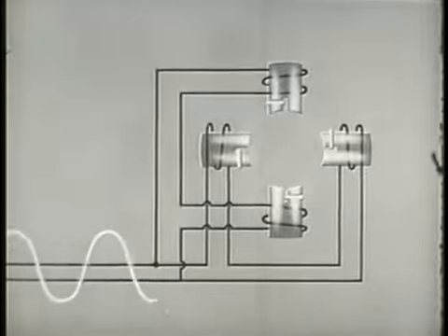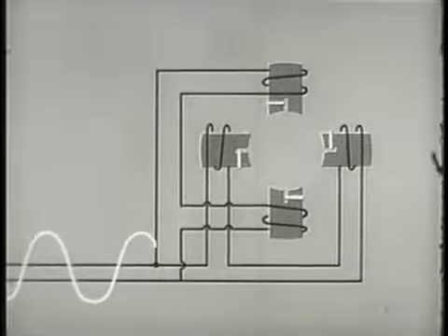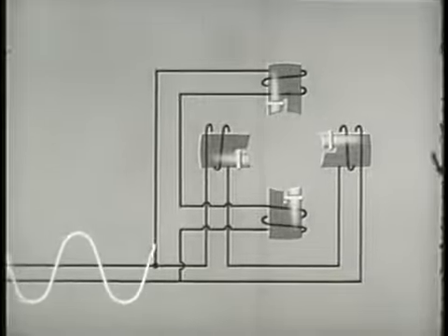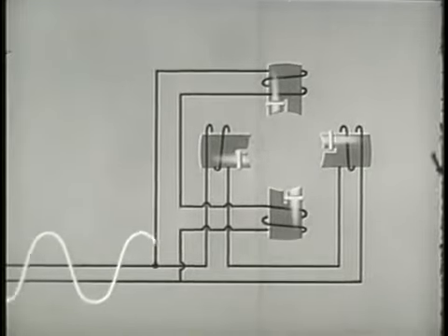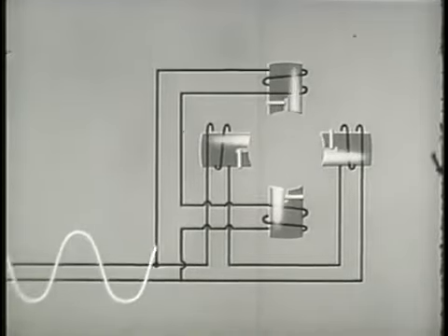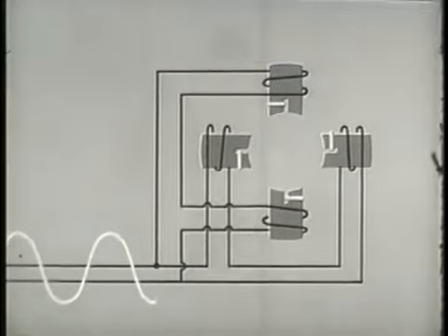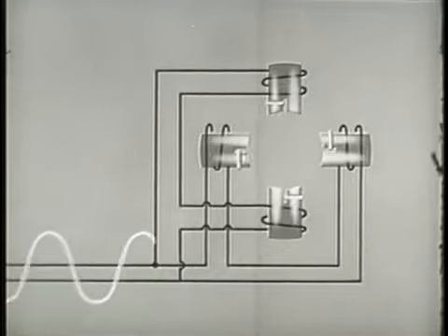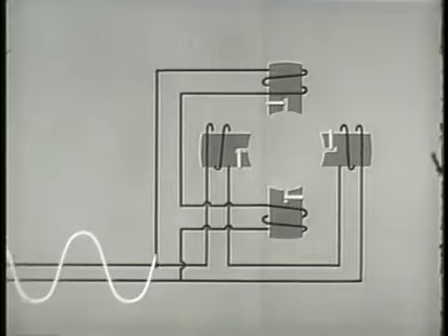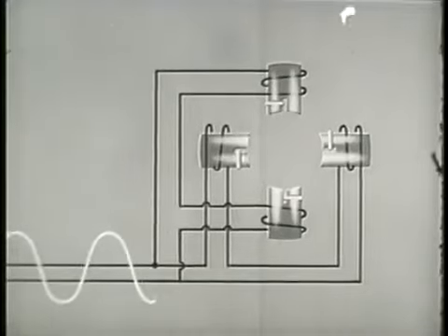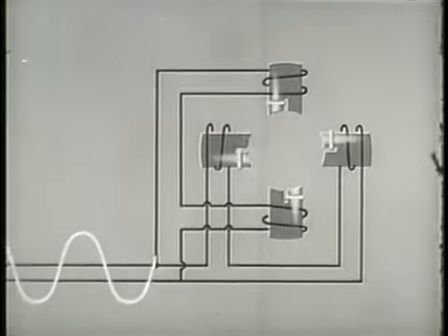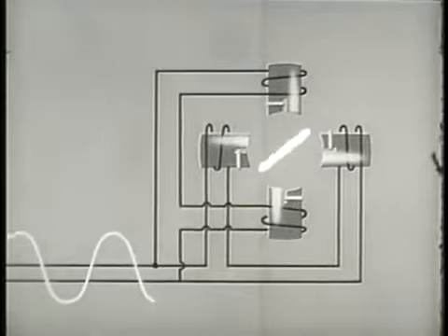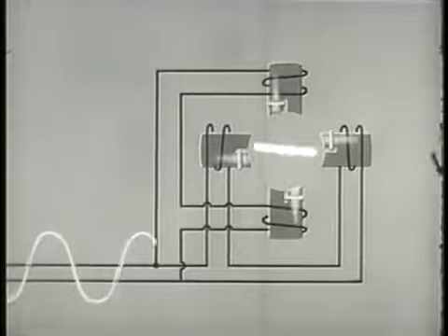The single-phase AC energizes the unshaded portions of the poles first and creates magnetic fields in these areas. The phase difference caused by the higher inductance of the shaded sections is responsible for the lag in the development of magnetic fields in them. As the current cycle changes, the same action will take place in all the poles. Relative motion, the basic requirement of an induction motor, has been satisfied. The rotor turns.